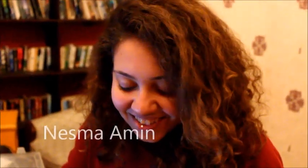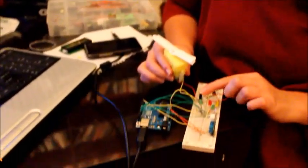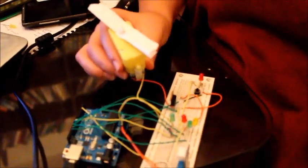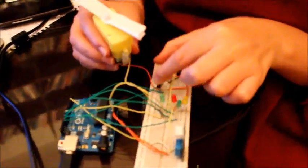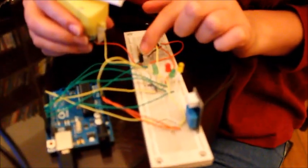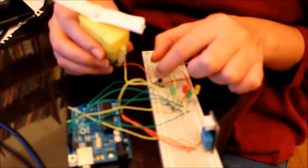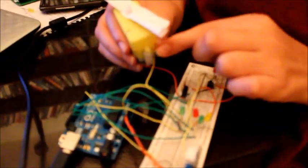Hi, I'm Nisma Amin, and my part in the project was to implement the temperature sensor as the first input and output to the DC motor, and an LED that shows if the temperature sensor is connected or not. In order to control the DC motor, we had to connect a transistor to allow the current, just for a certain condition when the temperature is greater than 20 Celsius. Other than that, the DC motor should not work.